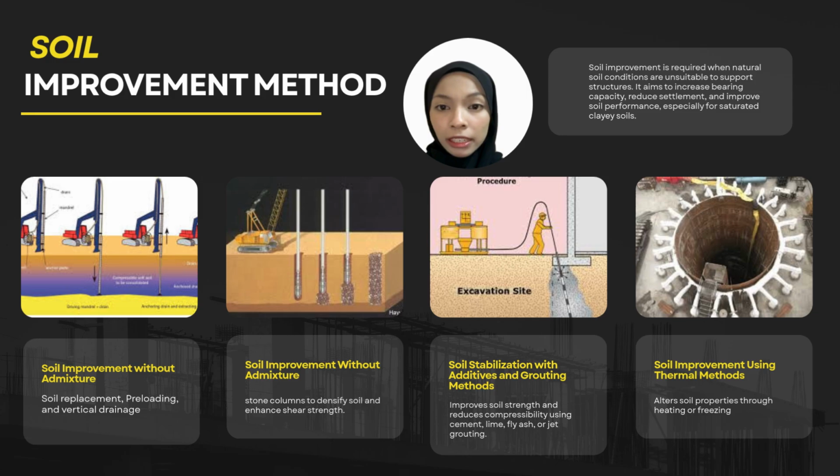Before starting any construction project, understanding soil conditions is crucial because natural soils may not always support structures adequately. To improve soil performance, several methods are commonly used, especially for soft or saturated clayey soils. Broadly, soil improvement techniques are divided into four categories. First, soil improvement without admixtures, which includes methods like soil replacement, preloading, vertical drains, and sand or prefabricated drains to enhance drainage and reduce settlement.